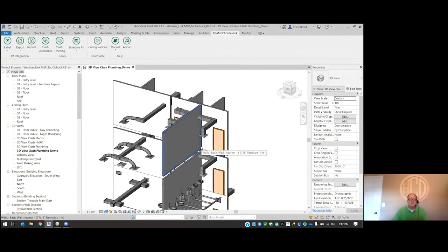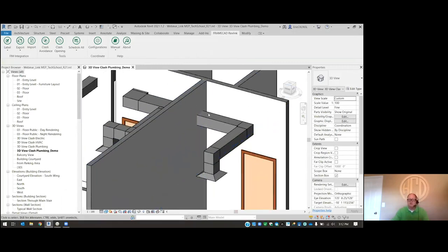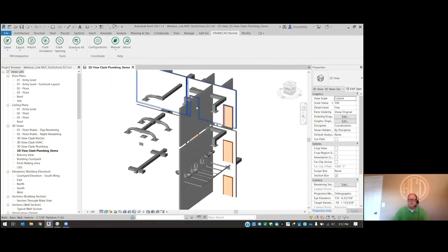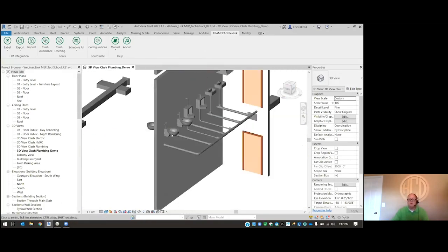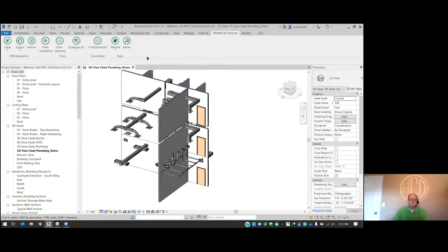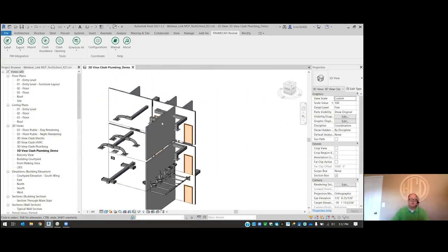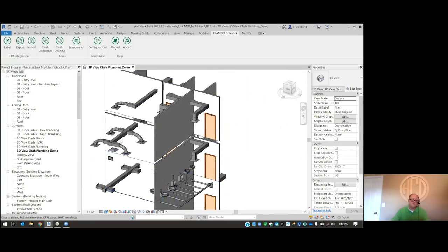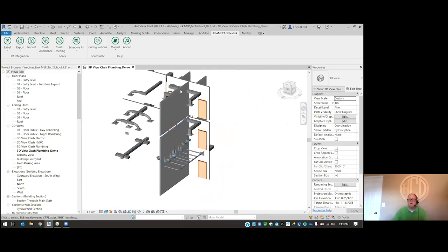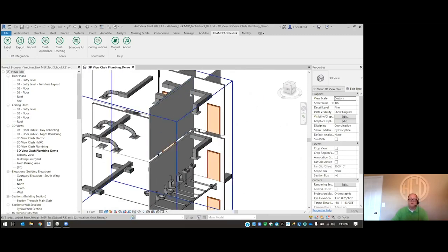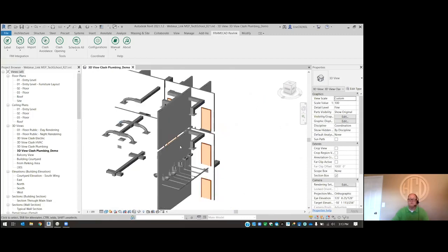And now the last tool that we'll take a look at is the clash openings. We have HVAC penetrations in our walls. We have plumbing penetrations and things like that through our wall. So now we can use our clash openings tool to detect clashes for MEP type elements, where we can then create openings. We can then export these wall panels with openings where these clashes would occur.